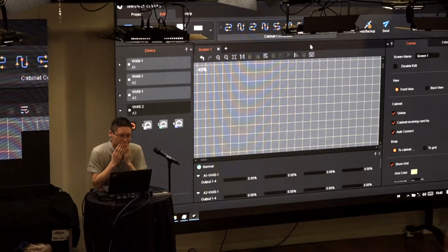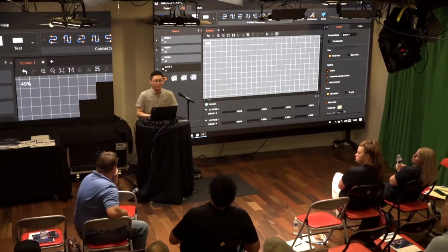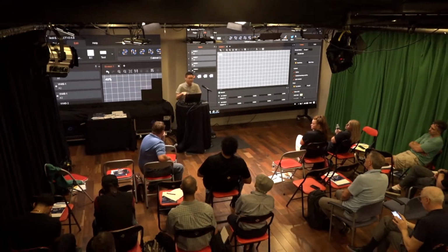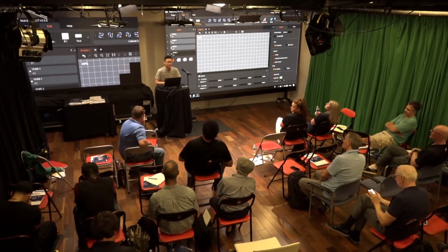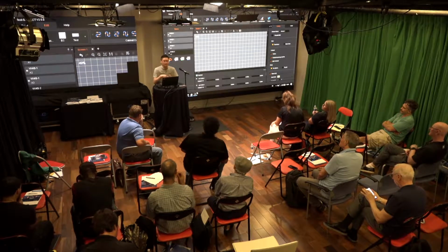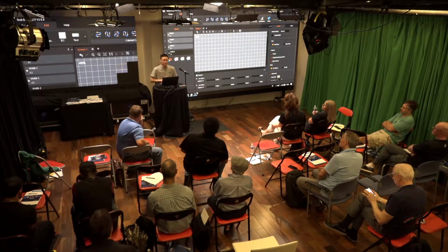So what if my config file is RCFG? How would I change that? You have to go to the LCT software and save it again. Save it as an RCFGX file. And will it give you that option in LCT? Yes, you can load this file and save it again. Use the higher version software to save it, and then it will automatically be changed to RCFGX.